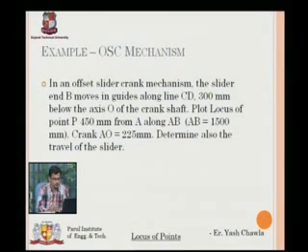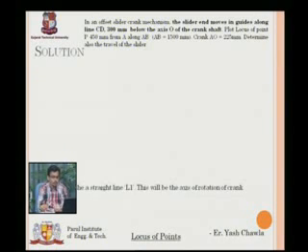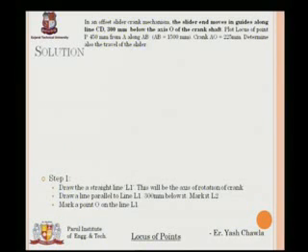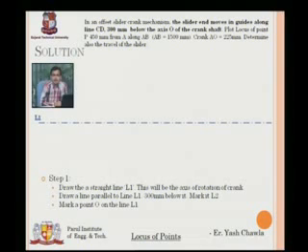So let's move. The first step, what are we going to do? Any guesses? Nobody is there. So let's see. The first thing we want to do is draw the reference lines: the reference line for the rotation of the crank and the reference line for the reciprocation of the slider. So here we go. This is line L1. On this line L1, I will have my crank that will be rotating.